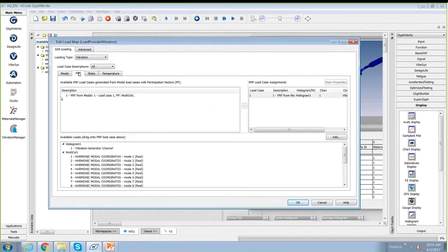The second input inherits that frequency response function, and you'll see it says for modal, and then I apply to that my PSD. So that is my input FRF, and I'm applying a PSD that came out of the vibration generator that I showed you the profile of. So that's the load provider.